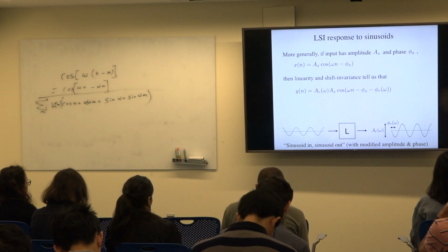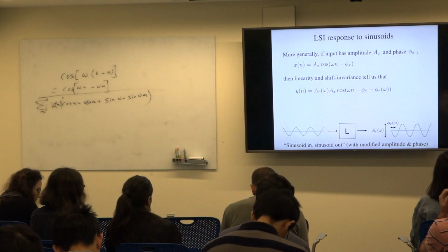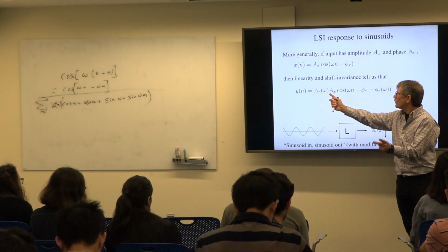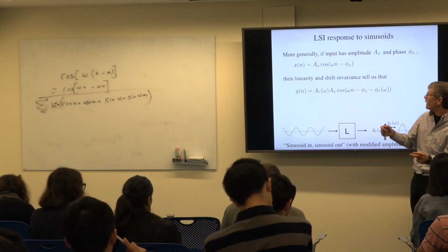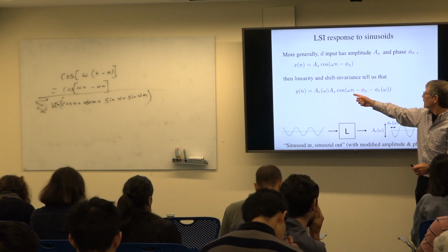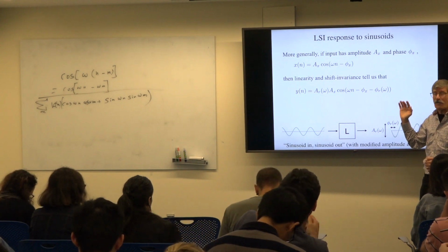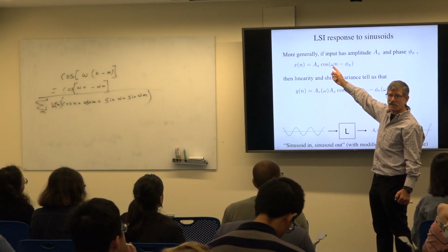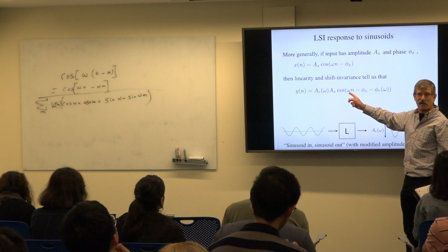I know that this new input is living in the plane, but what I've proven is that when it goes through your system, you're going to get another cosine wave of exactly the same frequency, possibly phase delayed by some amount, possibly amplified by some amount, which means it's going to stay in the plane. It's going to go somewhere else in the plane. It's still a linear combination of cosine and sine, because it has an amplitude A_R X, it has a delay, phi x plus phi r, and we know how to treat that and where that is in the plane. So any cosine of any amplitude, any phase of that frequency goes through your system, and what comes out is possibly amplified, possibly phase shifted, the same exact frequency.